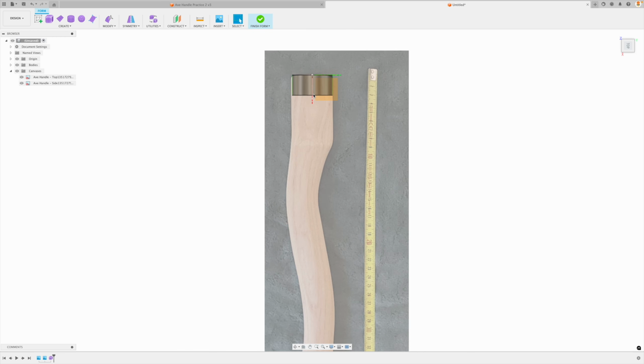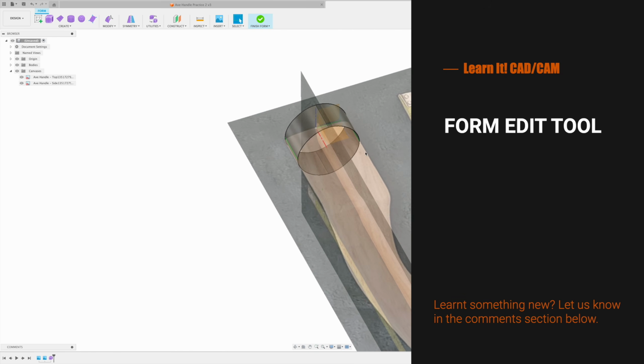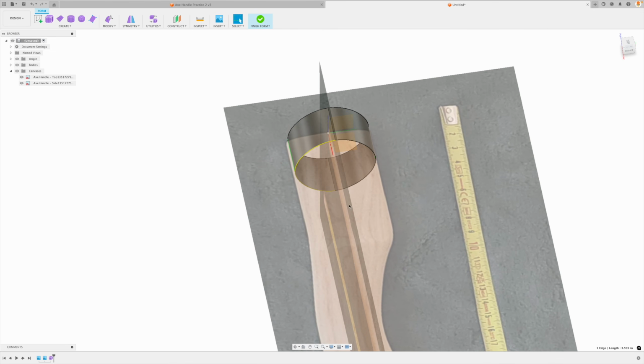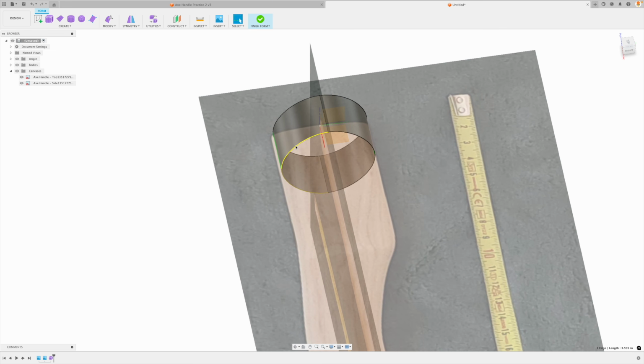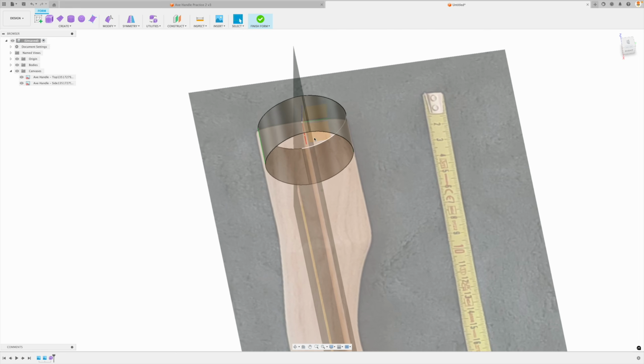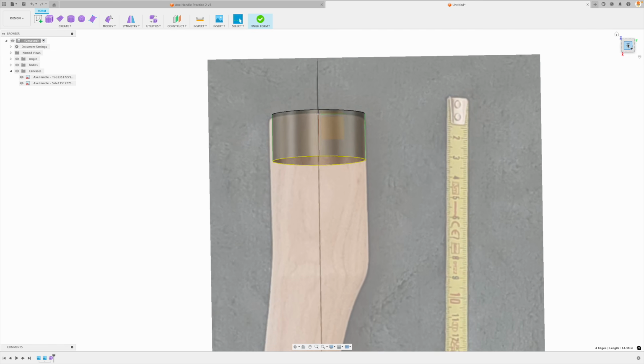And so this is just going to be fun. I encourage you to follow along with me, and let's just get it done. So what I'd like to do, just for ones who haven't experimented with T-Splines or form models, is we can pick a single aspect, whether it be an edge, a face, or a vertex. And we can pick multiple vertices if we want by holding down Command or Control on Windows. But if we wanted to pick an entire loop of something, you just double click and you see how it picks that entire loop. There we go.